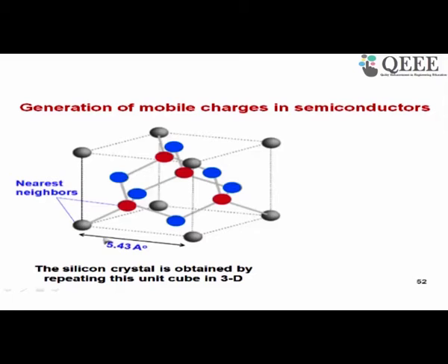So here a silicon unit cube size is 5.43 angstrom. So you can see in this cube you have atoms at the corners of the cube. So 8 corners, then 6 face centers. The blue atoms here are at 6 face centers. So the cube has 6 faces, and then you have 4 atoms inside, 2 near the bottom diagonal corners and 2 near the top diagonal corners, which is perpendicular to the bottom diagonal. So it is something like this.